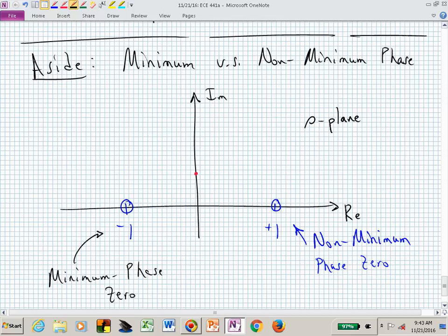I simply walk over to the real line, to the imaginary axis, and then go up to omega. So now I have this Pythagorean theorem. I can now find the hypotenuse, and that's the length from this 0 at minus 1 to that red dot, to that frequency. Or I now have this particular magnitude for that frequency and due to this particular 0. What about if I had a 0 over in the right half plane and I wanted to know its length to that same frequency?